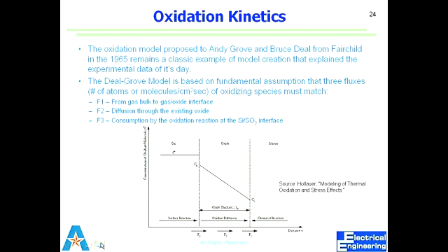Just like in diffusion, which is the process in silicon fabrication, what was the difference between unlimited supply of diffusant and limited supply? The concentration gradient. In unlimited supply, the distribution kept on increasing and the maxima didn't change.